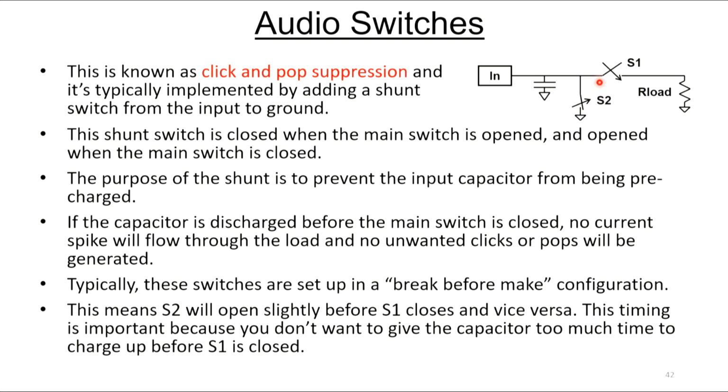You don't want a long time delay in here, because you don't want to give this cap a lot of time to charge up before you close your switch to bring in the load. Anyway, this just shows you what click and pop suppression is, if you've heard that term related to audio switches. That's what they're talking about.